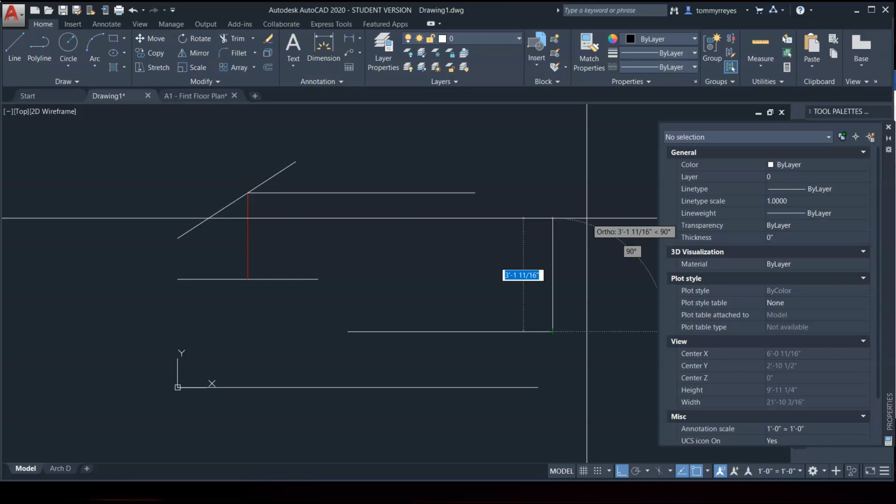And when I draw floor plans, or straight lines, perpendicular lines, I like to use ortho to give me a sense of security, with 1000% assurance that this is going to be perpendicular and not half a degree off and throw off my entire floor plan. I've had to redraw a floor plan once, and I just decided never again. And so that's polar tracking, and that is ortho, and that is on page 2-8, 2-9.